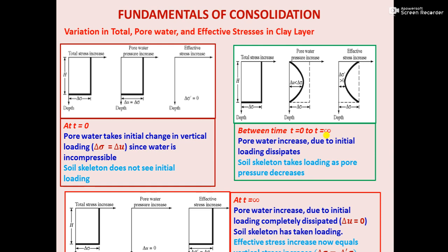So its process is such a lengthy process. However, you will observe at a later stage, when you will be doing mathematical calculation, that maybe out of this 100 years time, the 90% or the 80% consolidation in many cases will be happening in 50 years, 55 years or 60 years time. Okay. So this may happen, but as you see, from t is equal to 0, this years time we are taking, that is actually your infinite time. Okay. So this infinite time, when you are thinking,